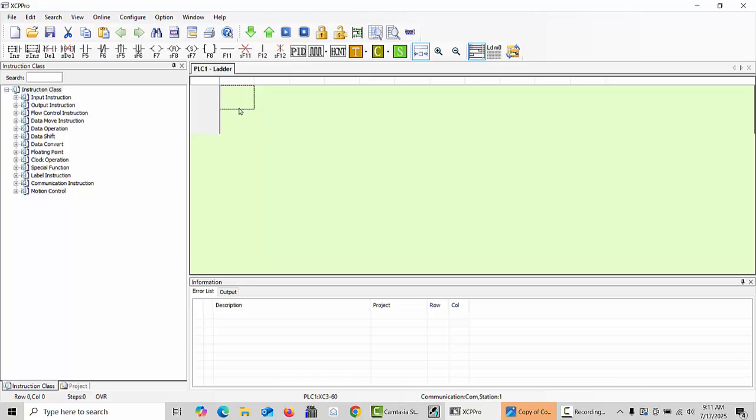First of all, we will take an internal memory bit, for example LD M0, the first bit, and click enter. Next we type this command, SFTL, for example. If we'd like to move the bits from right to left, we use SFTL.